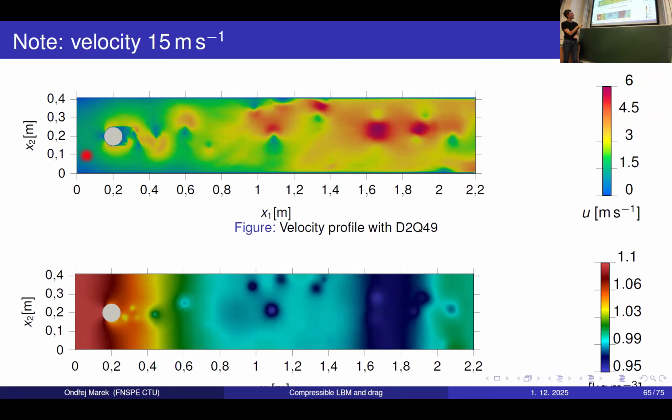You can see that the boundary layer is maybe just splitting from the boundary, and there are some very high velocities. Here the scale should actually be times 10, it just didn't change properly. And for the pressure, the difference is about 15% in the density, so in the pressure. And from this, maybe you can also see the equipressure fields behind the obstacle.